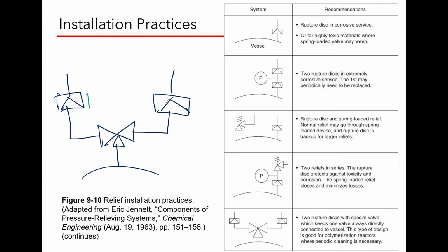you use valve 1 here, you notice that after a while you have a polymer deposit here. In that case, the pressure, because this one becomes very thick compared to the original layer, so what happens is the pressure needed to burst it is increased. Your set pressure is no longer the set pressure that you want, but an increased pressure now. And so if it reaches the set pressure that is supposed to burst, it will not burst because of the extra coating.